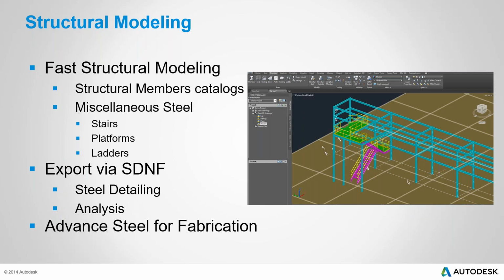When you're doing connection detailing, any minute aspect of that particular connection, from a base plate to a complicated pipe connection, every parameter could be tweaked in Advanced Steel. And while you're doing all these aspects, it could also take care of piece mark numbering, and you could utilize generation of drawings like your general arrangement, single part drawings, assembly drawings, etc.